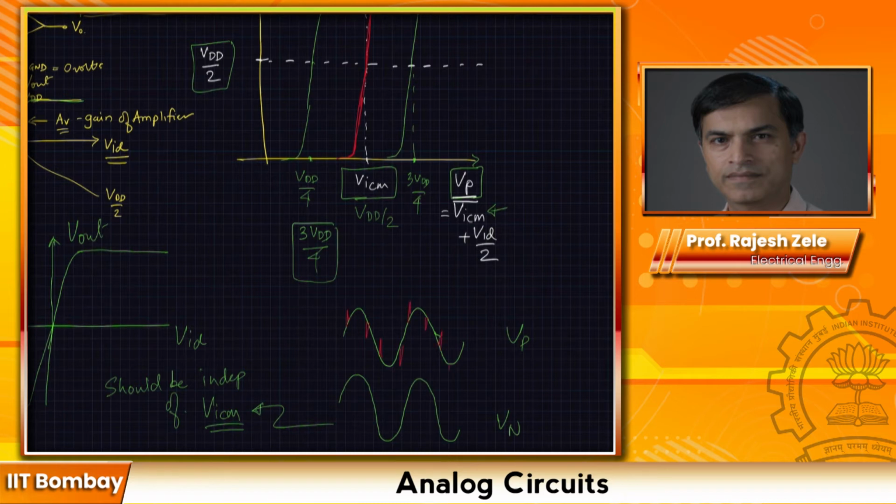Again, I'm exaggerating substantially, and then on this side it will be on the opposite side, something like this. Okay, so as you can see, the common mode, the green part, is the same on Vp and Vn. However, the red part, which is what we are most interested in, is going in the opposite direction on Vp and Vn, and that's the signal we are trying to amplify.